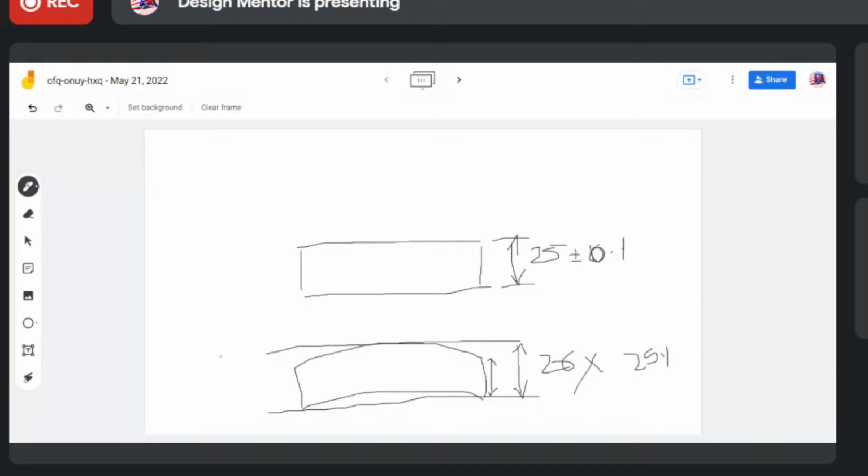So if a certain part, like I was telling you about certain screws, they've given a big hole so it fits easily, and you don't need it to be very precise. Like some instruments like gauges, the pins of those gauges need to be very precise because they are counting minute details. So according to the application, we decide what kind of dimension and tolerance we give. So that is rule one.